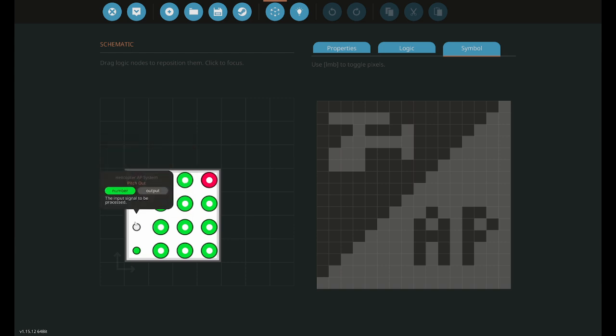This just goes out to your collective, out to your pitch, out to your yaw. That's all you need. You don't need roll input or output for this. So you can wire your roll directly to your gyro, or if you have another system to stabilize your roll, that's fine too. But I didn't build it into this because it was complicated enough as it was.